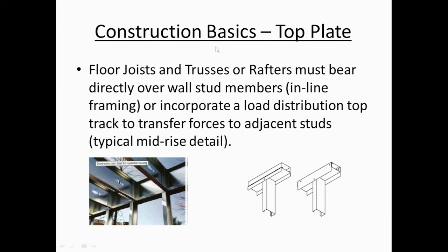Construction basics. Load path is something that is very important in any structural design, specifically in cold-formed steel framing as well, and that means that the load in these joists, as it comes off the floor into the joist, must transfer directly to the stud underneath. It must be a very clear load path.